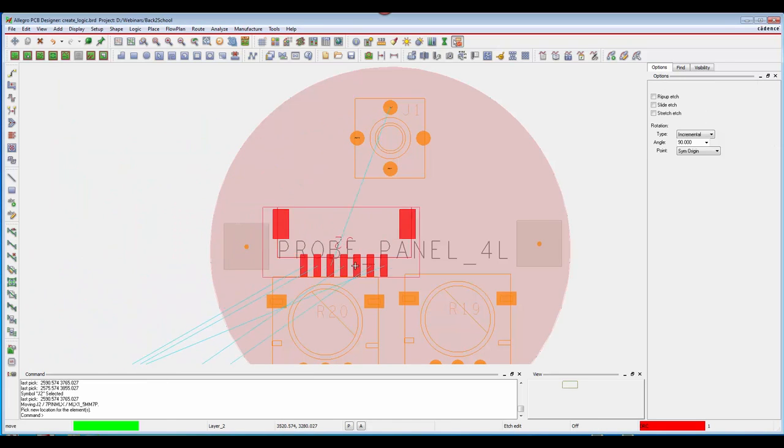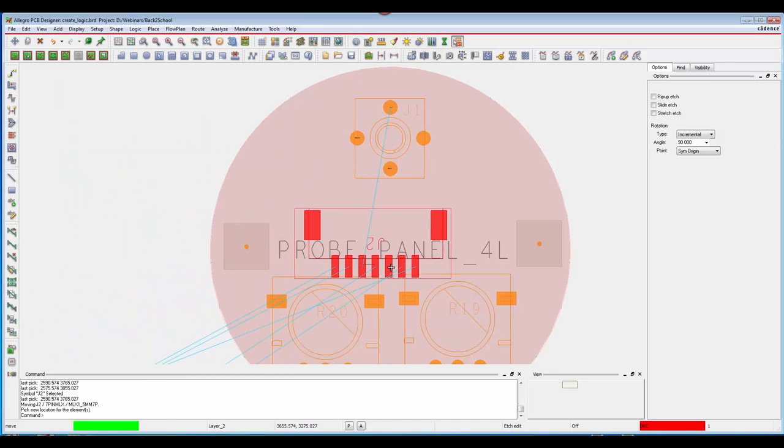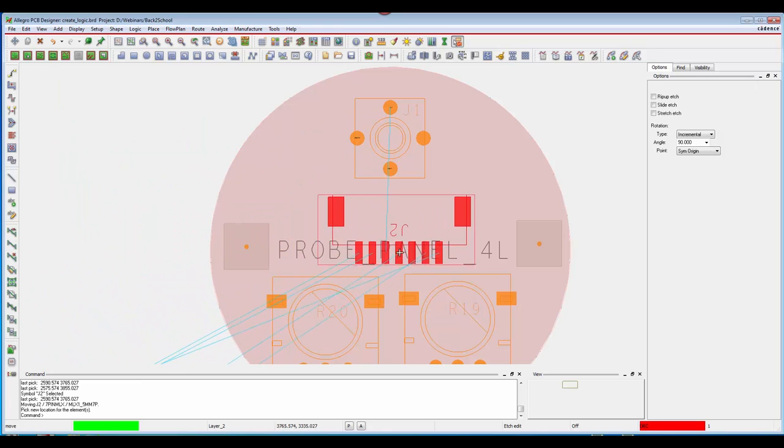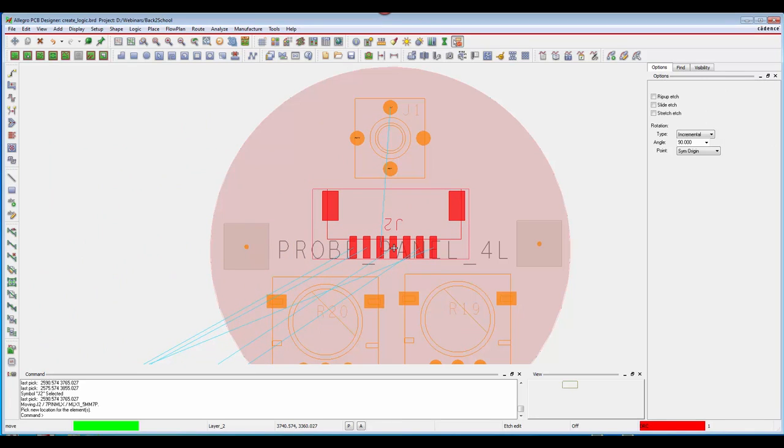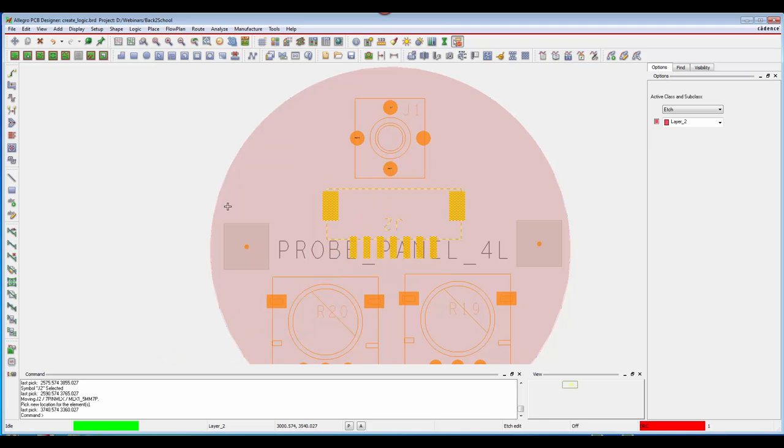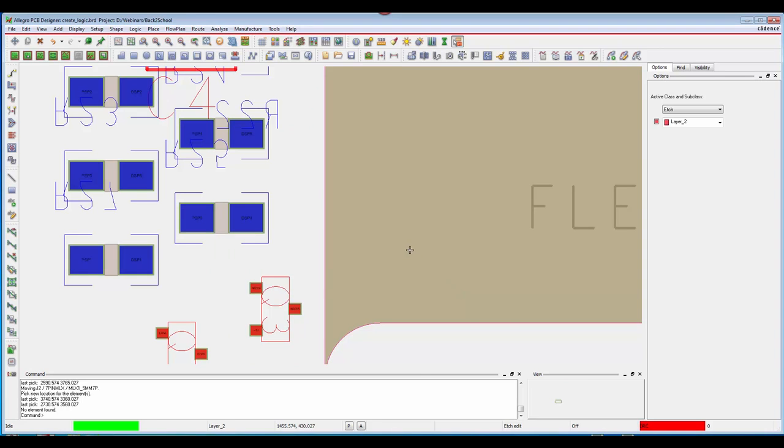I have here a symbol that was placed on the outside of the design, like a lot of us do before we do our placement, placing them around the design, and it was placed on the top. It's highlighted by the red component leads. And now I'm placing it onto a 4-layer of my 6-layer stack up. And we see the leads are now pushed down to the top of that 4-layer package.